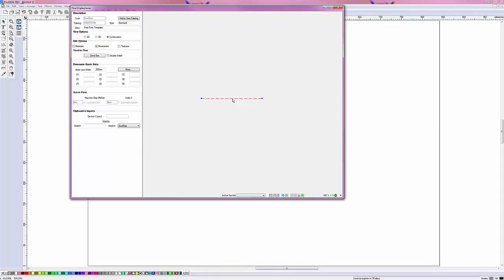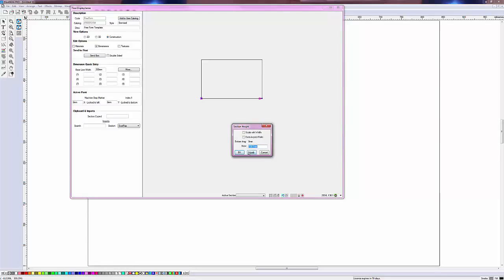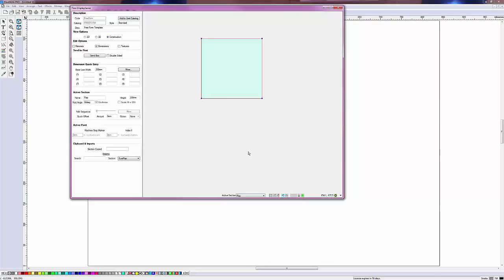Now I add the first face, at line, add basic flap. Now if I left click now, I'll get a face of an arbitrary or sort of estimated dimension. So I want to enter an exact number. I press period, and now I can type in 200 millimeters in here.